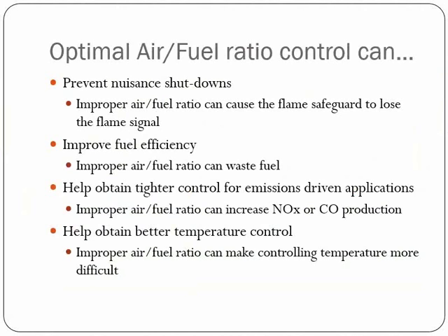Optimal air-fuel ratio can also help obtain better temperature control. When we look at just maintaining a temperature, certain methods of air-fuel ratio control provide better resolution, meaning that a small increment in the temperature control signal will actually physically move the valves, allowing it to react and adjust properly and maintain tighter control.